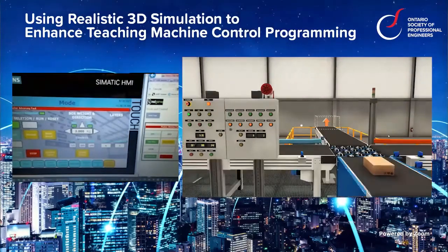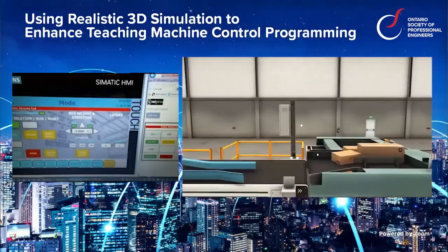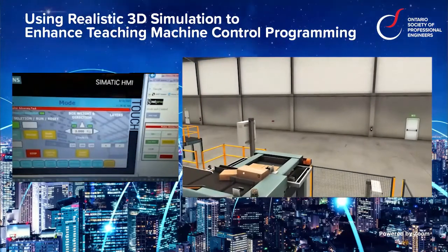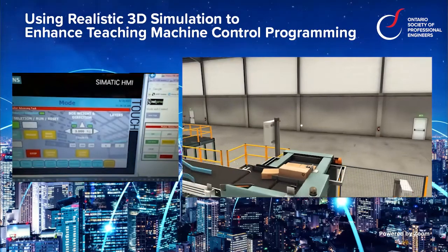So there's a good chance that if I go over to the elevator here, I'm going to see a jam up because I put that big box in the way. I now have that pusher. It never went all the way forward. Actually, that box got jammed up on that extra proximity switch I added. So now I'm stuck. Now the operator's stuck. He's in manual mode. He's got to clear this fault. So this is a perfect opportunity to take a look at manual control.